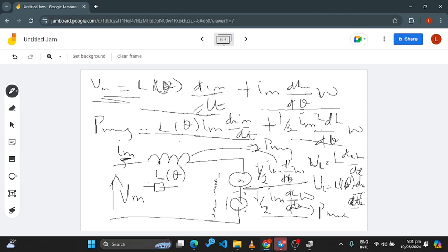So then I can draw this circuit. This circuit just summarizes everything. It says that this plus this guy plus this guy, if you add the power that is dissipated in them, that should give you the magnetizing power, and the power dissipated in this guy here is what gives you the mechanical power.